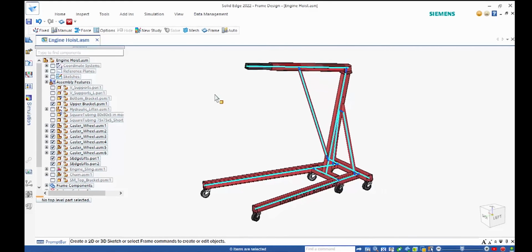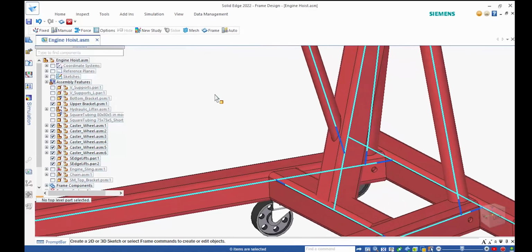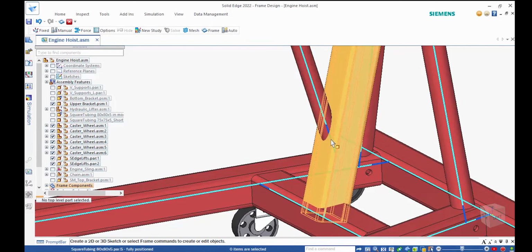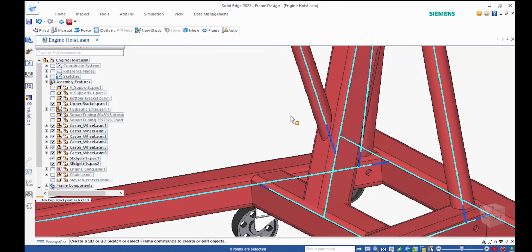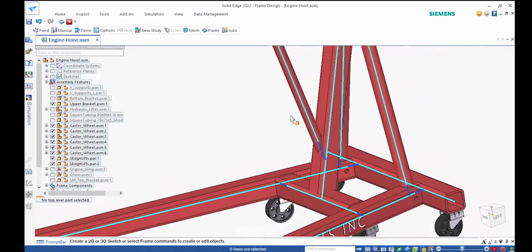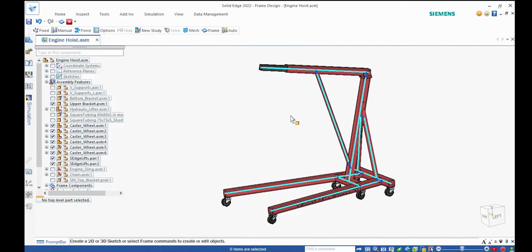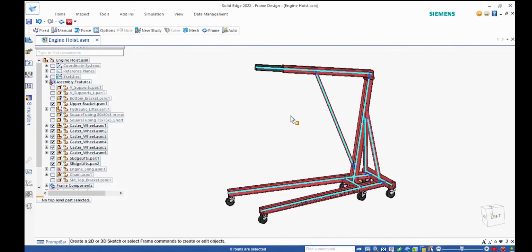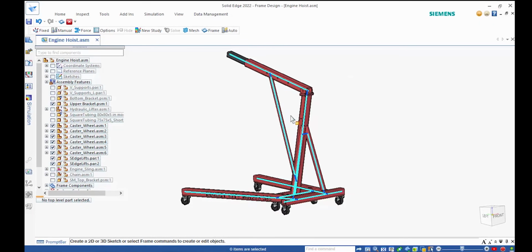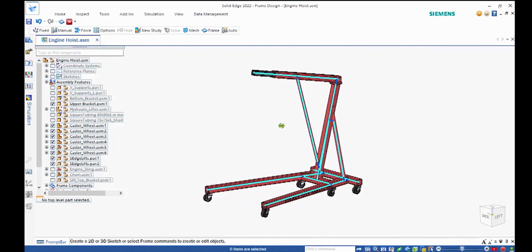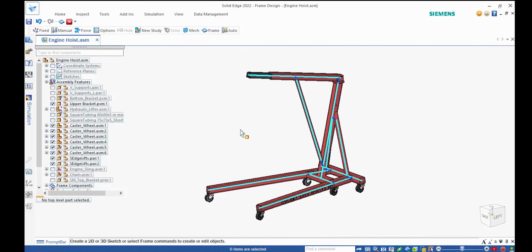beams. One thing I'd like to point out is that it connects elements with what we call rigid links. And this is a very powerful way of connecting elements and quickly getting results. Not only can we do it automatically, but I'll show you later how we can do it manually, and it will improve productivity drastically. So in this case, I automatically connected and extracted all the beam elements.